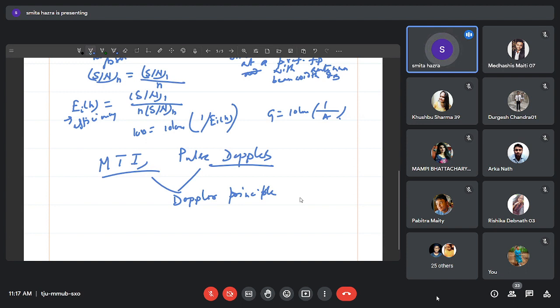So when your target or object is a moving one, then along with the range we also have to specify what the velocity of the target or object is, what the acceleration is, and what the direction is. These things also become very important for moving target indication. For MTI and pulse Doppler, actually one is range unambiguous and one is Doppler unambiguous.